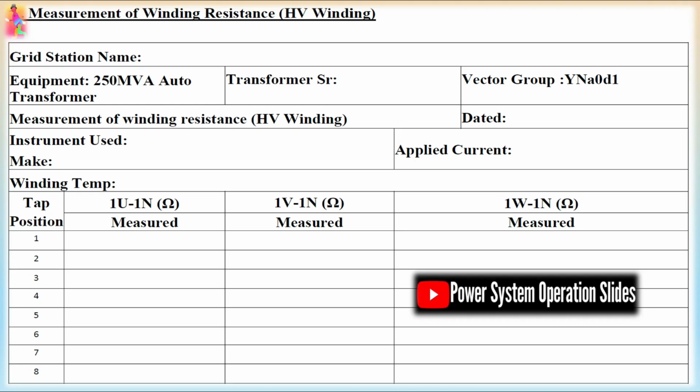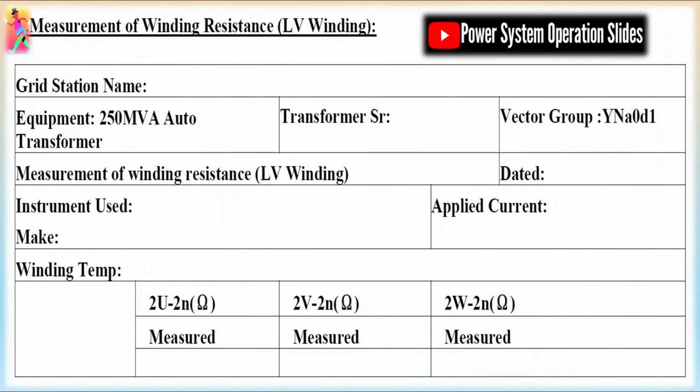of the raw measurement. Correction algorithms compensate for the thermal expansion and conductivity variation of the conductor. Failure to perform this correction can obscure true changes in winding condition and hinder meaningful comparison of results over time. Ensuring accurate temperature compensation enhances the diagnostic value of the test.